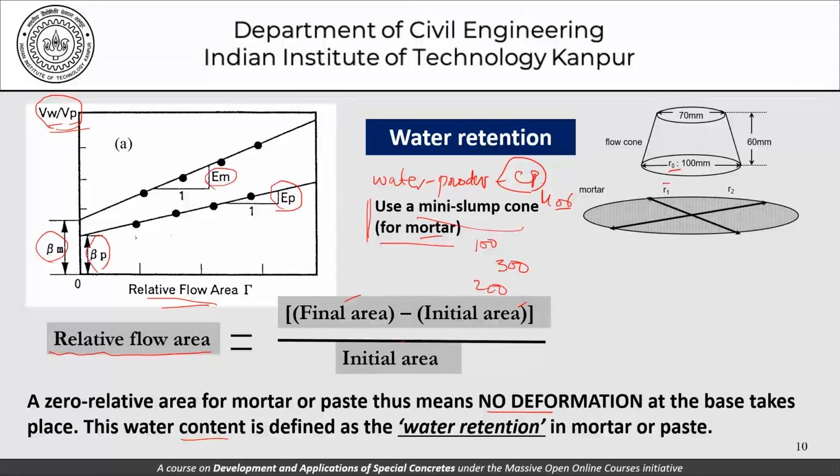So this is another simple experiment which tells us how we can try to better understand the characteristics of our powders and how the water powder ratio with that material would change the flowability of the mortar or the paste. Having done that, we are better equipped to predict the flowability of the concrete. Now these two experiments are an insight into what engineers do to understand the flow behavior of concrete.